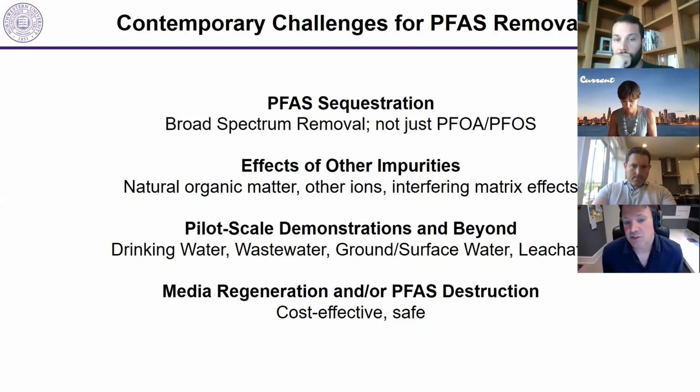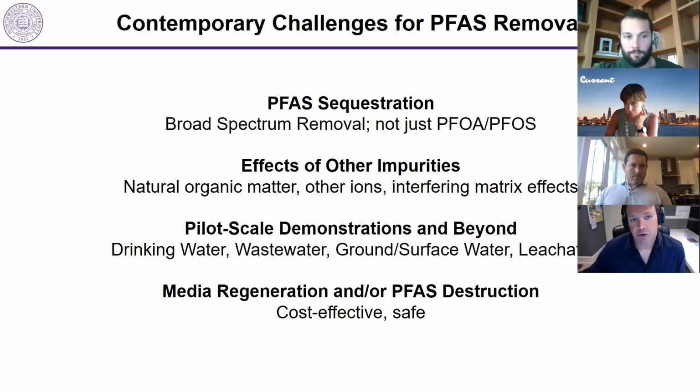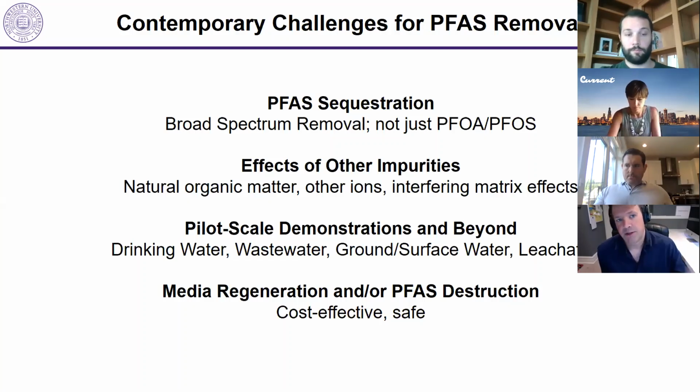And then finally, the final solution in talking about PFAS destruction, and this is a very, very common question for people working in this area, is what do you do with the PFAS after you've removed it? And so in terms of removal technologies, if one is working in absorbents, if they can be regenerated, that's a potential advantage, but inevitably you're going to create either a solid or a liquid waste stream or waste product that is contaminated with PFAS. And it's becoming more clear now that current ways of burning activated carbon, for example, that are contaminated with PFAS are problematic. It contributes to the problem by putting these things up into the air.